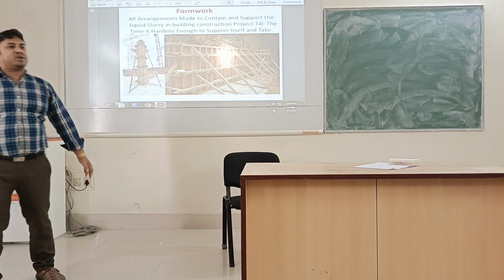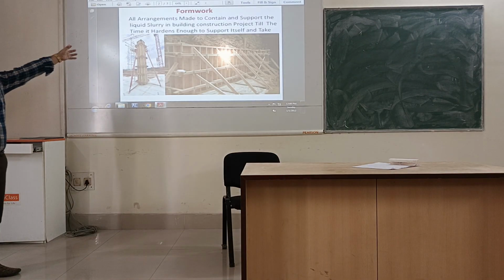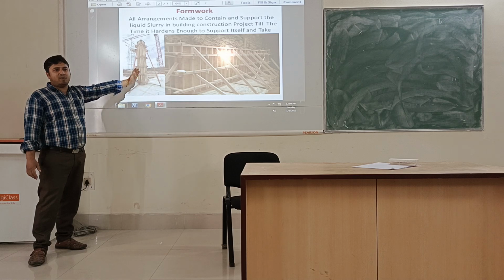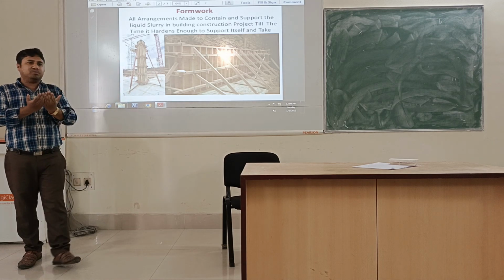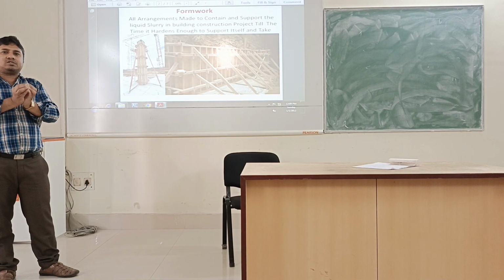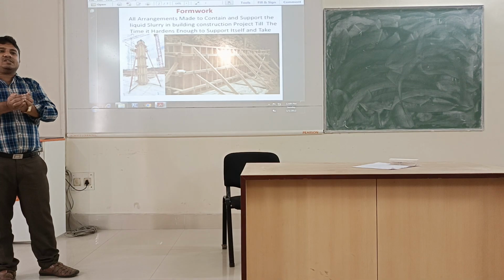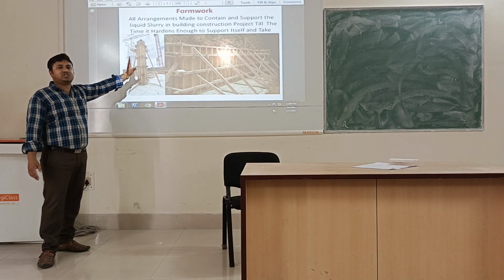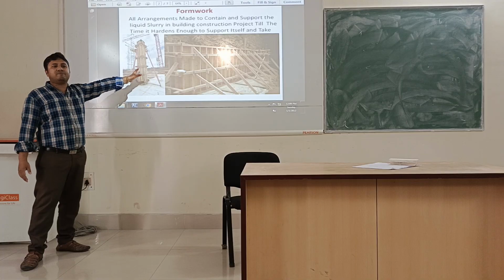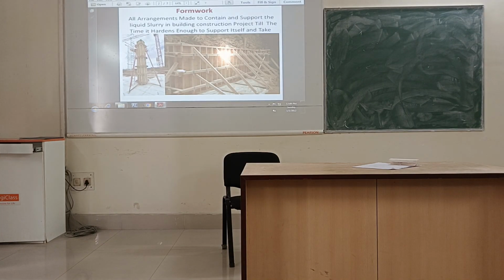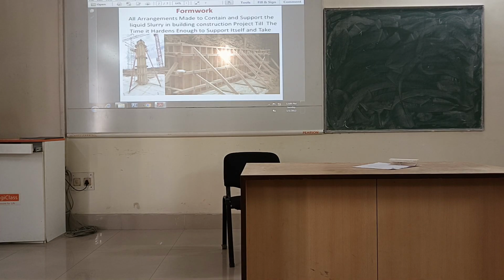And what shape would this formwork be? It can be made of a simple rectangular or square form, and it can also be used for a circular form. By combining two concentric hollow cylinders, they can be made as a cylindrical column, and by using four sides of square plates or shuttering plates, we can make the configuration of a rectangular column. This is called your formwork.